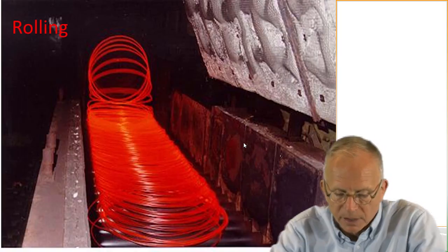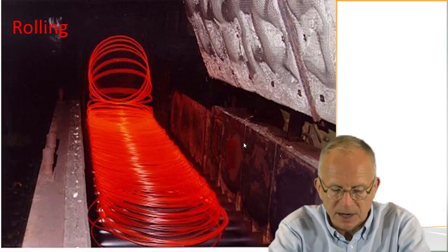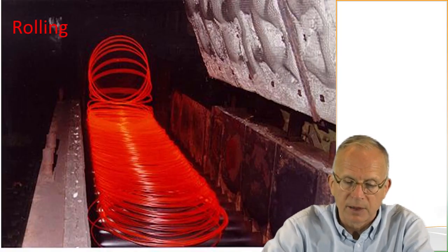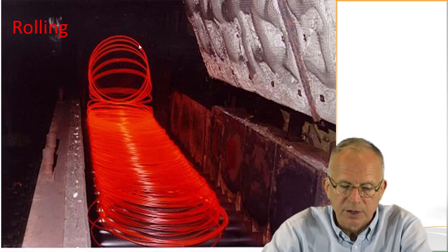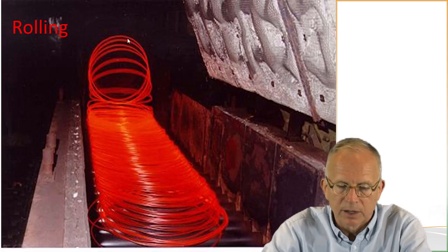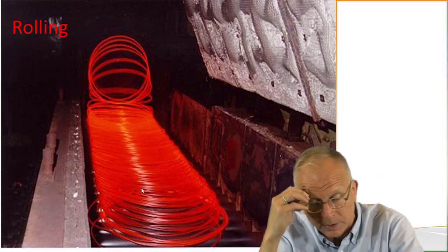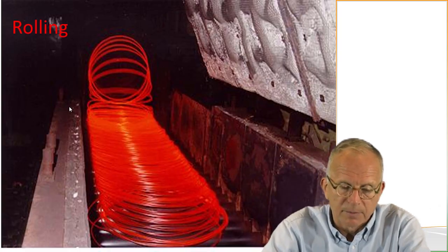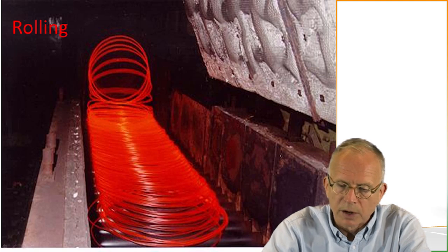Rolling. Also, Simmons now has bought Morgan Construction, and they make rolling mills here in Worcester. So here is some rod or rod-like material coming off a rolling mill. You can see that it's quite hot by the color, and that it's going into loops because it comes off so fast that, if you didn't loop it, it would be hard to control. The other thing here is you can see some heat treatment, and controlling the heat loss, you have these doors that you can put down to change how fast this is cooling off.